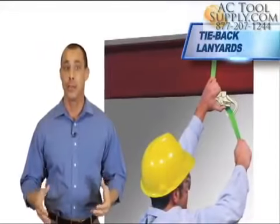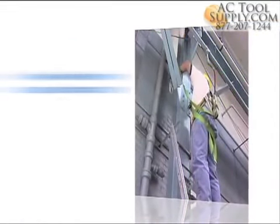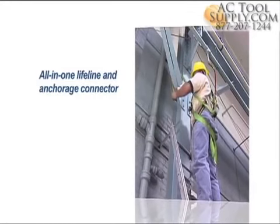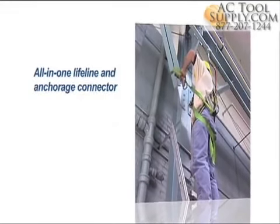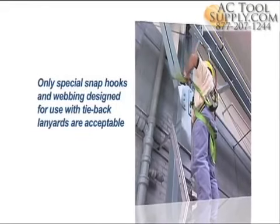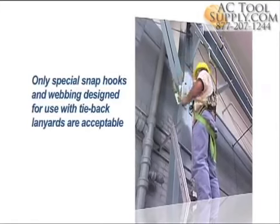Tie-back lanyards are a type of connecting device available as a lanyard or personal fall limiter that have a special snap hook and high-strength webbing that is designed to tie back anywhere along the lifeline. This all-in-one lifeline and anchorage connector increases safety and reduces equipment required on the job site. Only special snap hooks and webbing designed for use with tie-back lanyards are acceptable.